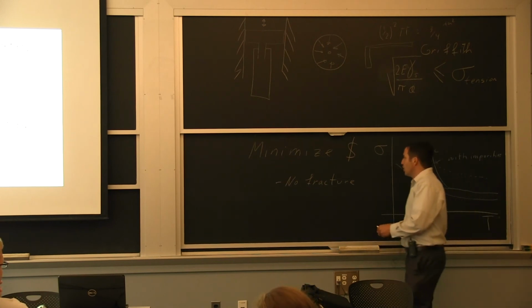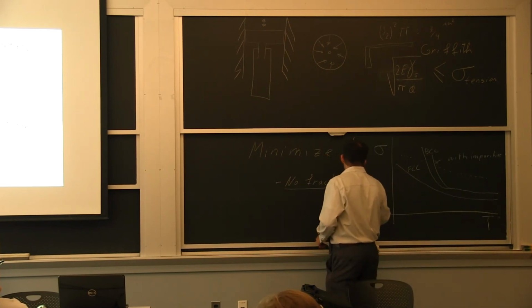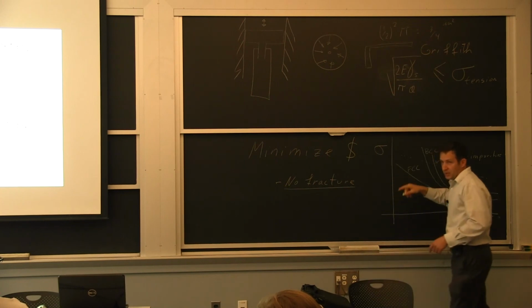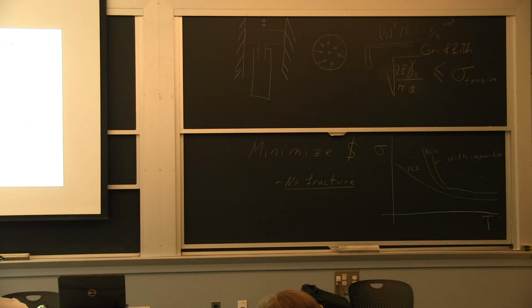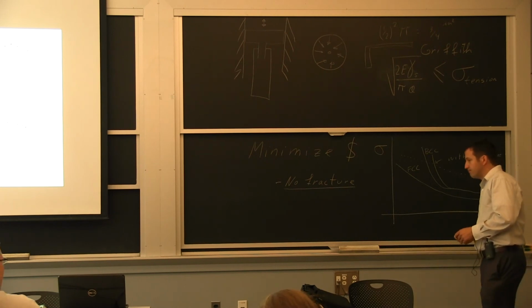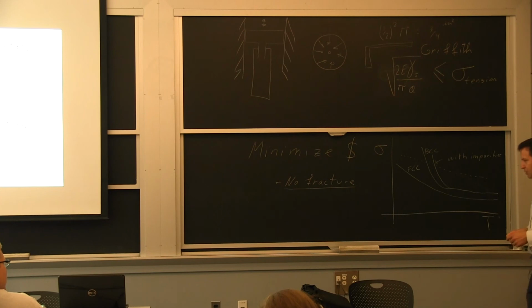So when you say I don't want a fracture, you have to work both ways, relatively independently. And I'm giving the example of temperature, but we should also talk about the effect of heat treatment on the alloy. There's some high-strength steels that are notch sensitive.